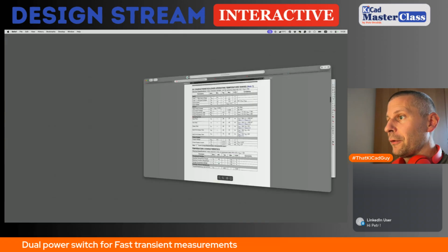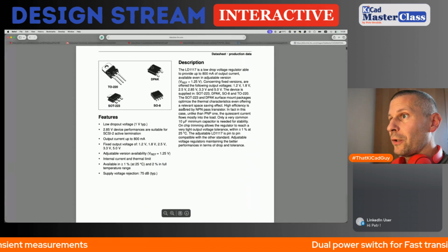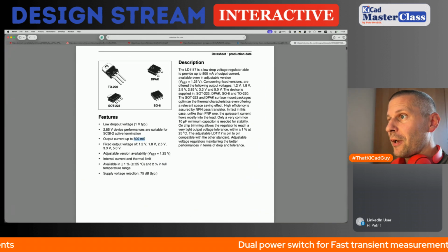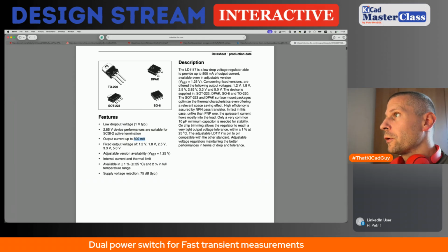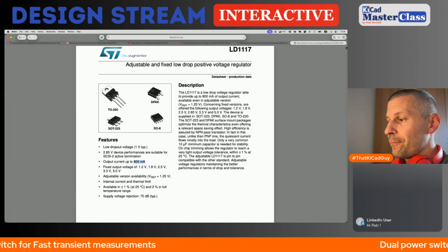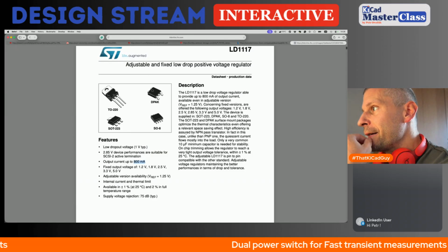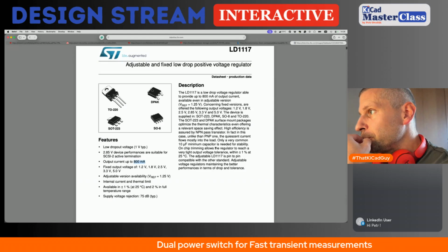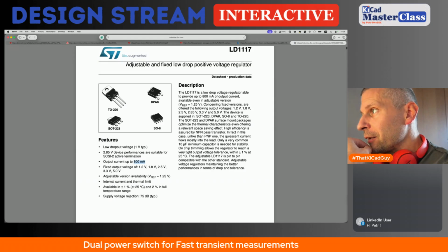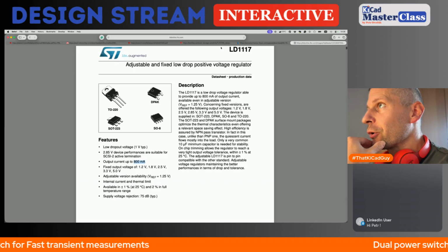Yes. Note 1 says that tested during, okay, not production tested, not a problem, but this LDO is pretty simple, easy to use, but the maximum current is only 500 milliamps, and I don't know what is the maximal peak current. We can help us using battery of capacitors at the output of the LDO to cover the peak currents, because the peak currents will be very short.